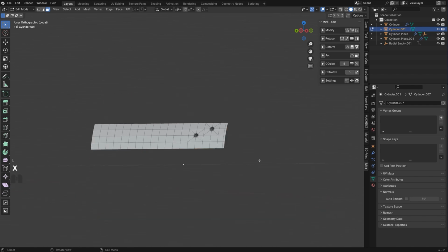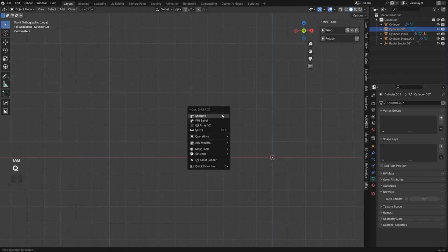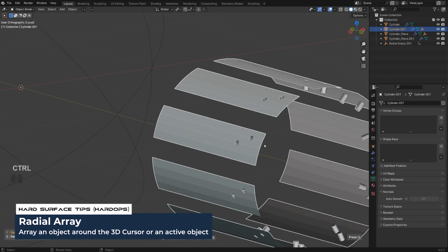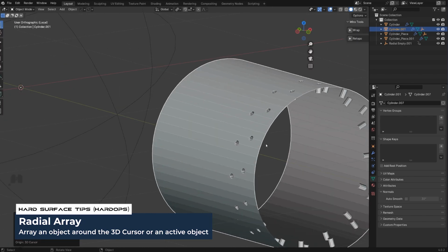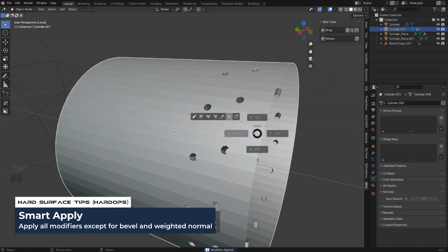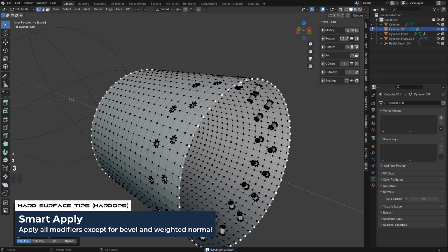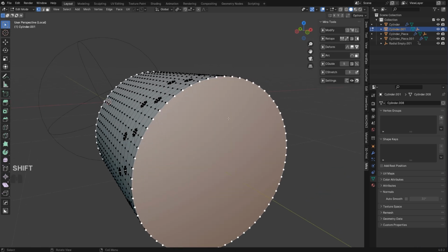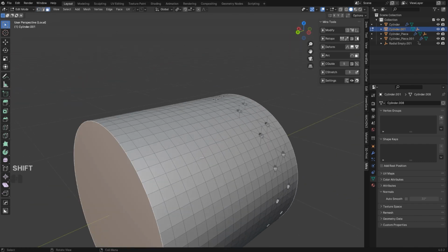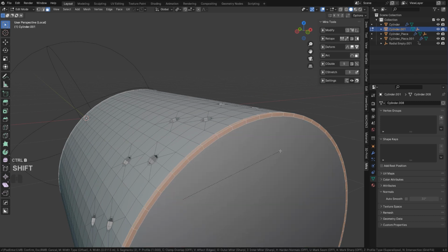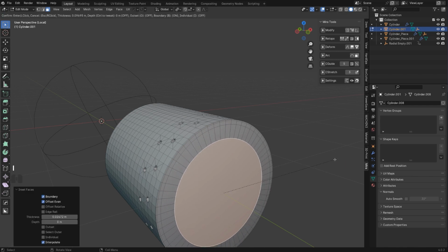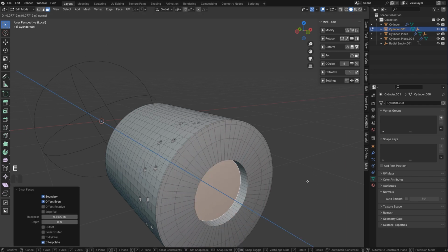L faces. Number 4 is a kind of a magical number for sub D for most things. Radial array, scroll up till you merge them like this. Q, operations, multiply. 3 to clean whatever is left over there. Remove this edge here. Select these 2 and run a really tight chamfer here. I mean bevel. Inset it closely here, and one more time like this.